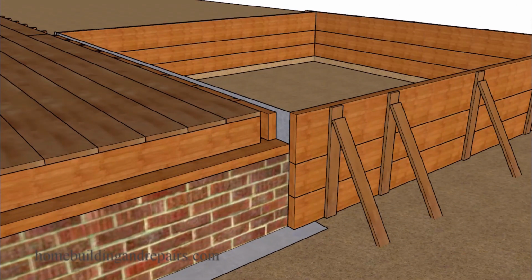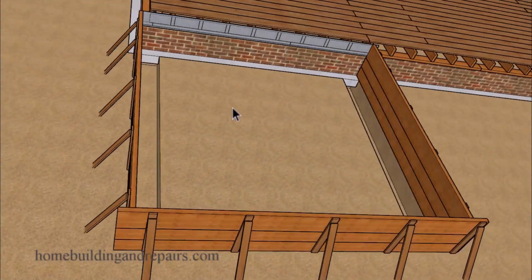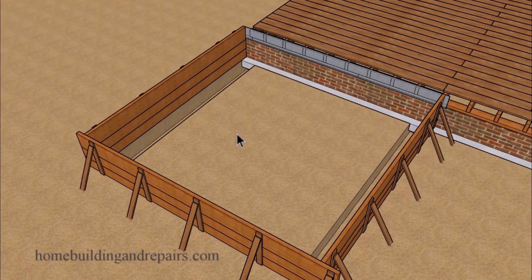So the first thing I want to do is put a piece of sheet metal, run it across here to protect this side of the framing from any moisture that could come from this side over here. And for those of you who don't know what moisture does to wood, I would suggest watching a few more of our videos. So we are going to create a form that will go around the perimeter of our building,